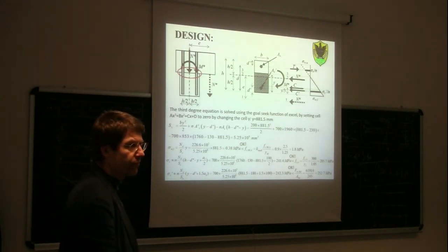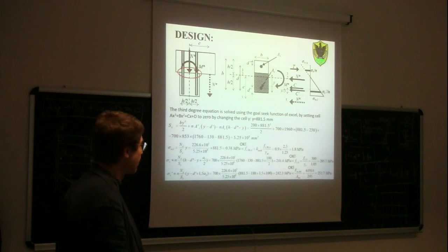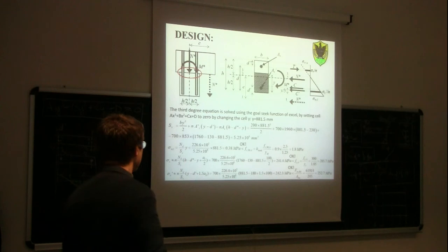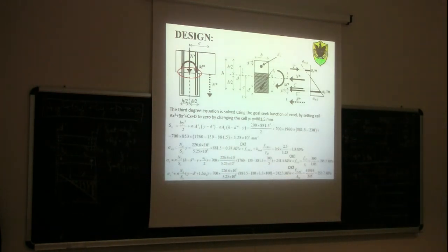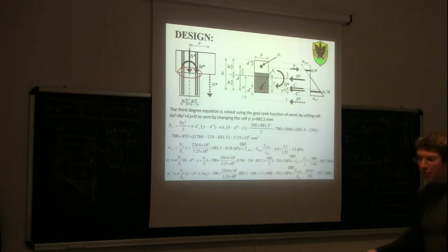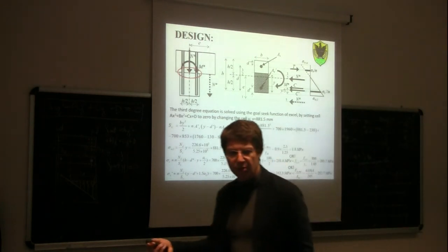So if this is the verification, where do you expect to have the first failure in your elements? So then we are checking 3 different components. We are checking the wood, the steel of the compression bars, and the tension bar. Suppose that the load is going to increase until you have an exceptional rod. What would you expect to be the failure mechanism?